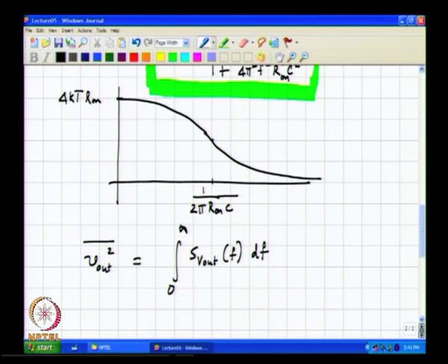Of course, you must bear in mind that none of what I have told you is really rigorous from a random processes or communication point of view. But in this course obviously it is not possible for us to get into mathematical details of spectral density and so on. All that I am interested in giving you is some feel for why those formulae make sense. You understand now why the mean square value is simply the integral of the power spectral density.